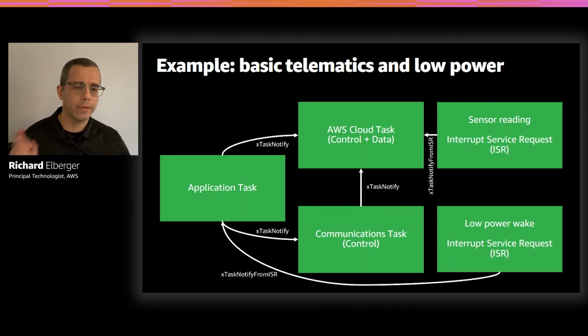And going a step further, we can put the MCU into sleep mode as well, right? To save even more power. And microcontrollers have these low power features, usually have a clock or a wake up pin or both, right? That enables us to manage that effectively. So when you're working with low power mode, just realize that this is another area where FreeRTOS can really, really help you. Since if you're working with tasks effectively, which I'm sure you are, you will be able to manage and bring up and tear down these tasks as you go in and out of these states.